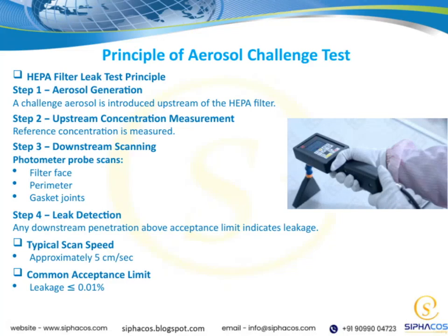Let's walk through the principle of the aerosol challenge test for HEPA filter leak testing. First, we generate an aerosol challenge upstream of the filter. This means we introduce a controlled aerosol into the airstream before it reaches the filter. The goal here is to simulate potential leaks by seeing if any particles get through. Next, we measure the concentration of the aerosol upstream, which serves as our reference point. This measurement helps us understand the initial amount of aerosol present before any potential leakage occurs.